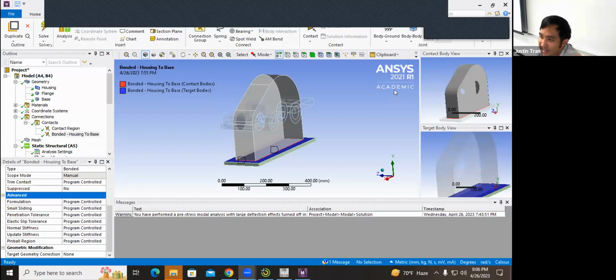In terms of design exploration, is there a difference between direct optimization and response surface optimization? They're different algorithms. So the direct optimization is the quicker option because what that's aiming to do is just give me the most optimal design parameters.